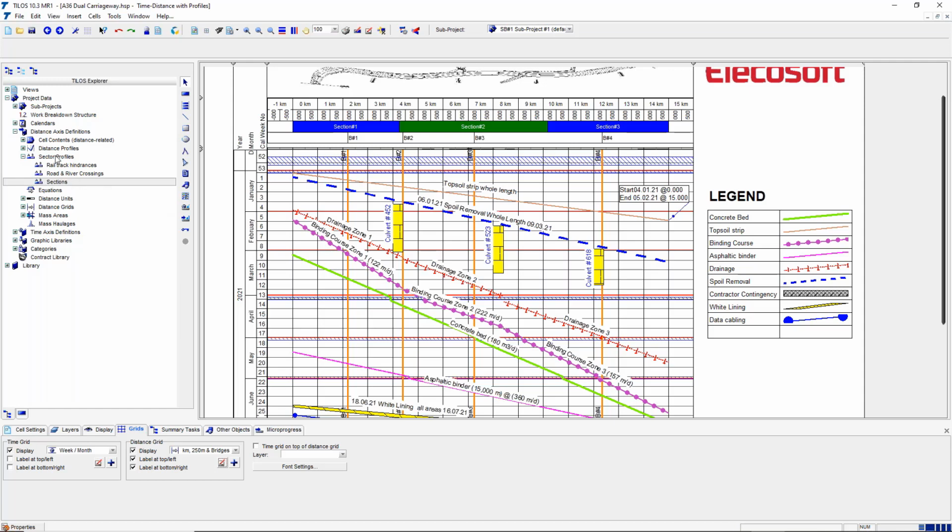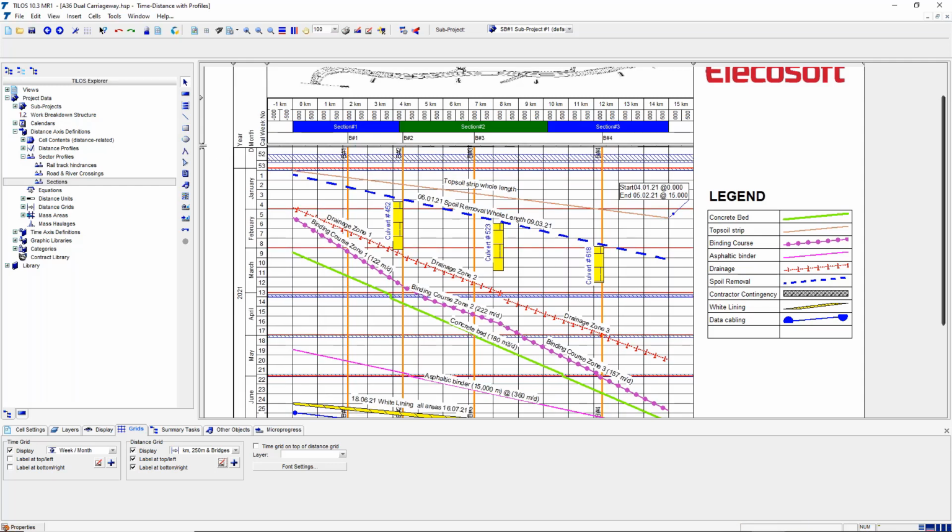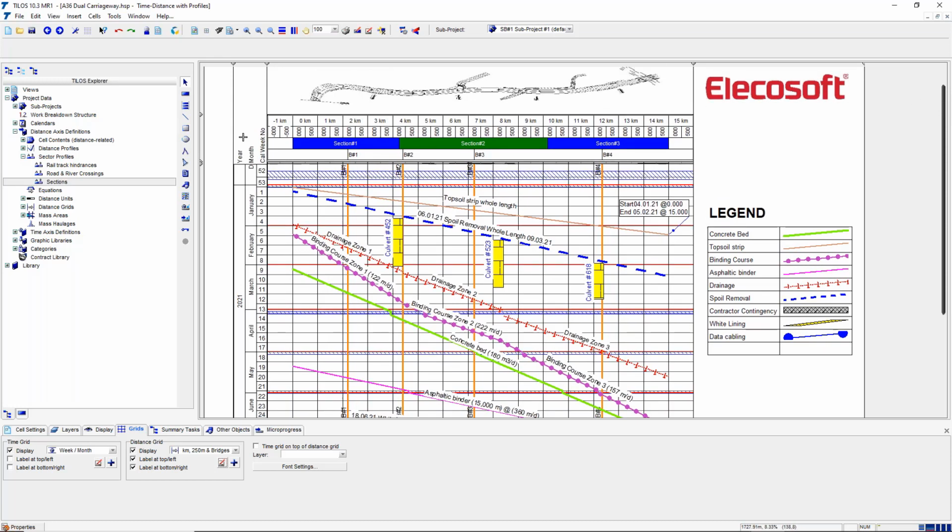So these sector profiles, as they're called, which is like a spreadsheet where you've got 2 distance values, are very, very useful, and you see that used time and time again to demonstrate interesting features on possibly both sides of the road or track, where you can pick out sections of, say, wooded areas or flooded areas or cut and fill areas, those sorts of information.